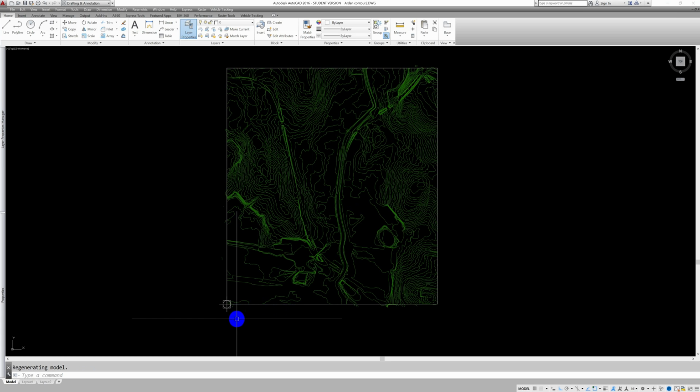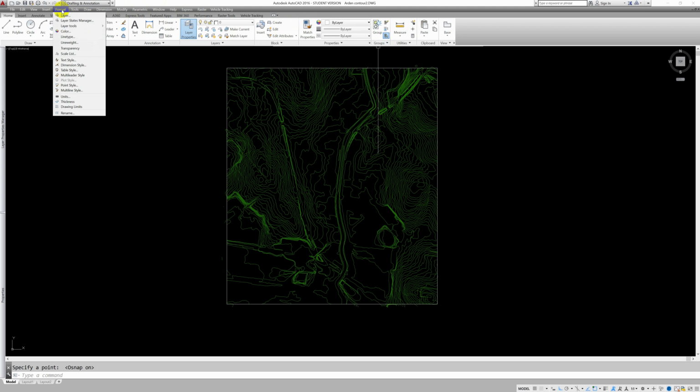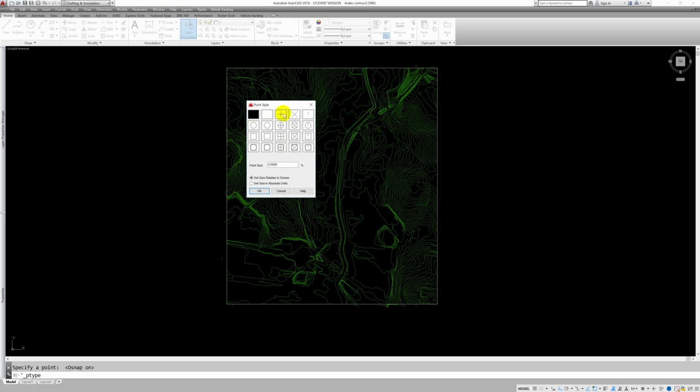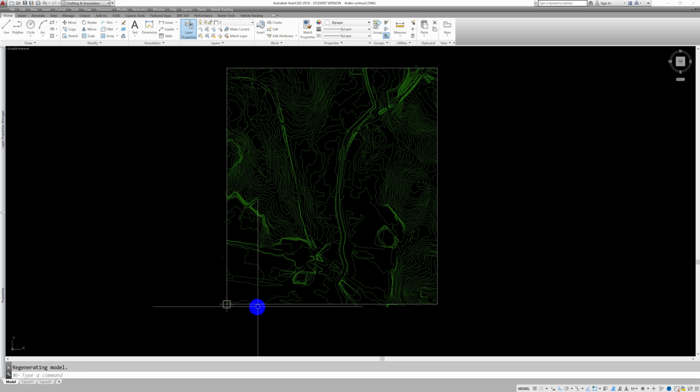I've then come up to my format menu and I've set a point style, and I've just made that point style reasonably visible so that I know where it is, because before it was just like an invisible point. What I can do now is I can type in UCS, and I will cover UCS in another video.